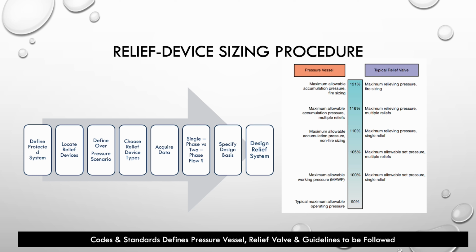Sometimes that's a pressure vessel. You don't want to be making it extremely complicated by inducing a weak point in the design by putting some weird fabrication point or a weak welding point around there. So most likely you're gonna find the overhead piping, the header coming out of the distillation column that's going to the condenser, most likely is gonna have that relief valve, because it's gonna be servicing the same purpose but with lower cost.